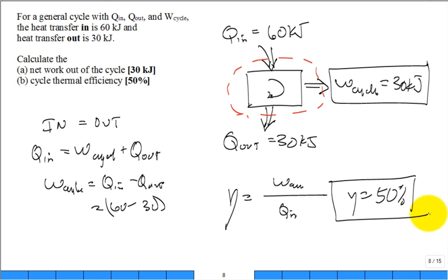When we get to second law analysis and the Carnot efficiency, we'll get an analytic expression for the maximum cycle efficiency, and it depends on the temperature hot that you're bringing Q in at and the temperature low that you're throwing the heat away at, and the maximum is 1 minus TL over TH. That equation looks too simple, but we have to work a lot to get to it. It gives us an upper limit on the thermal efficiency of a heat engine. Again, what does most of thermodynamics? Burn something to turn something.